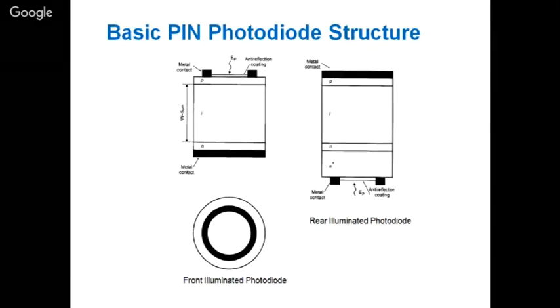A very thin layer of intrinsic material between P and N has improved this, and it has improved the detector, so now it is possible to detect picowatts also. This is the change they made to the PN junction, reverse biased of course, to get a detector for communication applications.